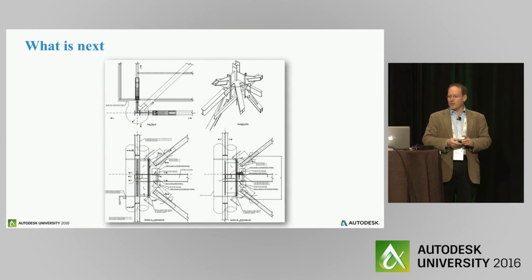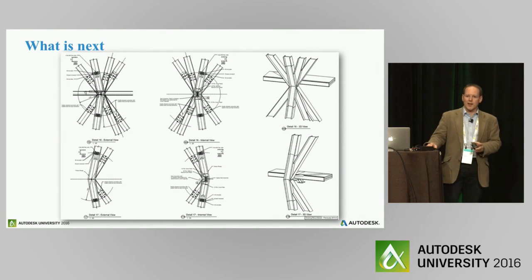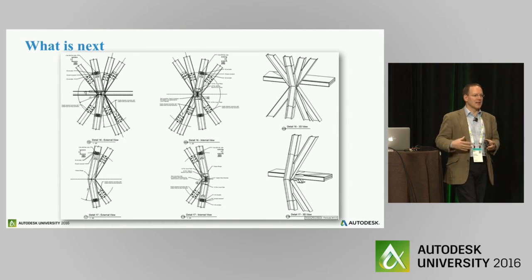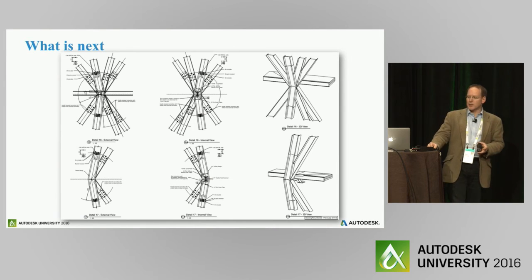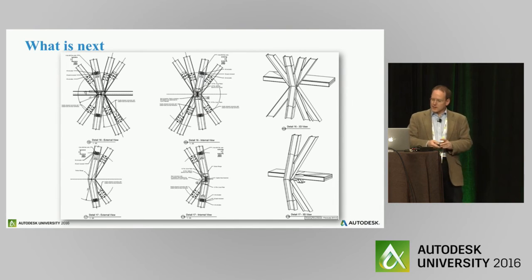And then a couple of other examples of the sorts of things we produce, where these connections, this one and this one as well, we as engineers have to know that what we're providing is fully buildable and designable. There's no point in offering up a connection to a contractor to design if that isn't the case. In many of the examples I've shown, we are, as an engineer, responsible for those connections as well. So the workload spreads the whole gamut of us, as engineers, being responsible, or the contractor being responsible. But ultimately, we have to know that it's buildable. So the tool allows us to take the output from, say, an Advanced Steel model and very quickly run through those options. So those are my examples.